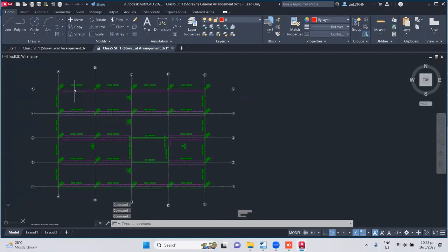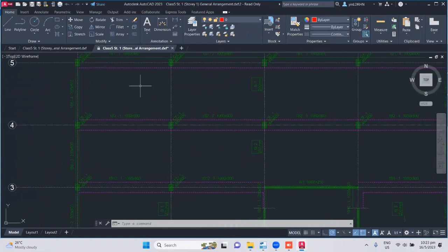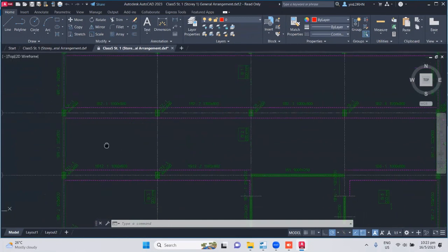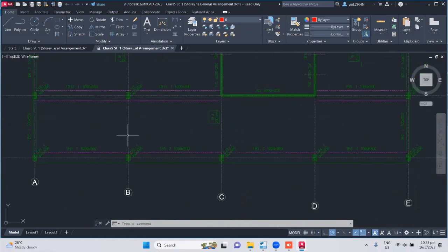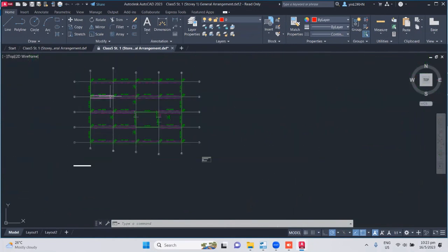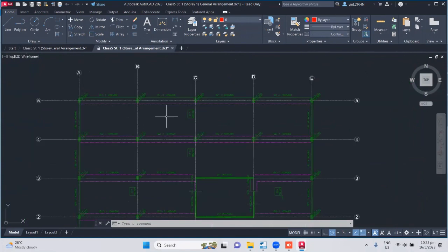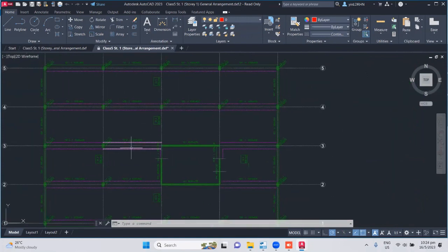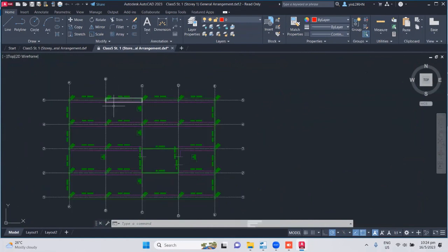See, all are dotted lines. Outside is a solid line because the slab stops here, right? So outside is solid lines. Our slab is not overhanging, so it's a solid line, but internal ones also are grid lines. See? Okay. So now we are producing our plan. So you don't need to go back and produce a drawing again. You can produce the drawings straight away. From here you can touch it up, you can share, modify it, but basically you have the base plan.